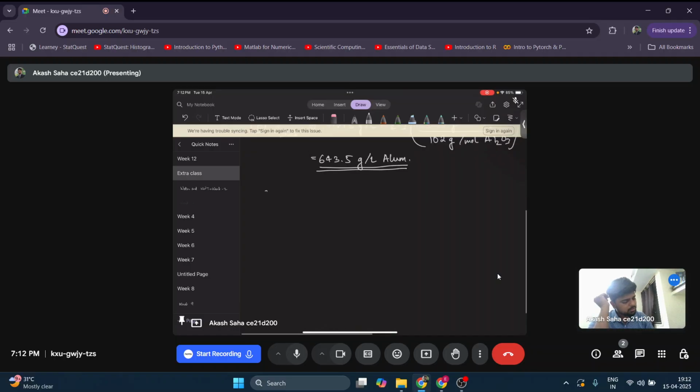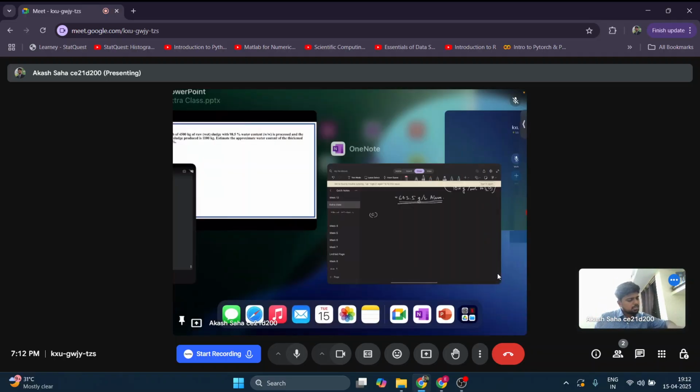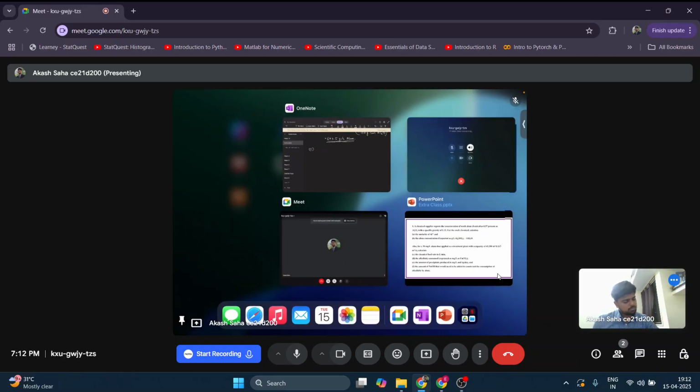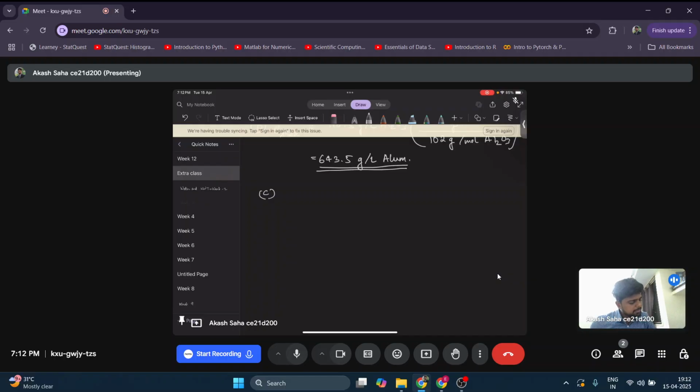What was the third part? Let's see again. The third part asks what is the chemical feed rate in liters per minute if a 30 milligram per liter alum dose is being applied. We just have to use the mass balance.